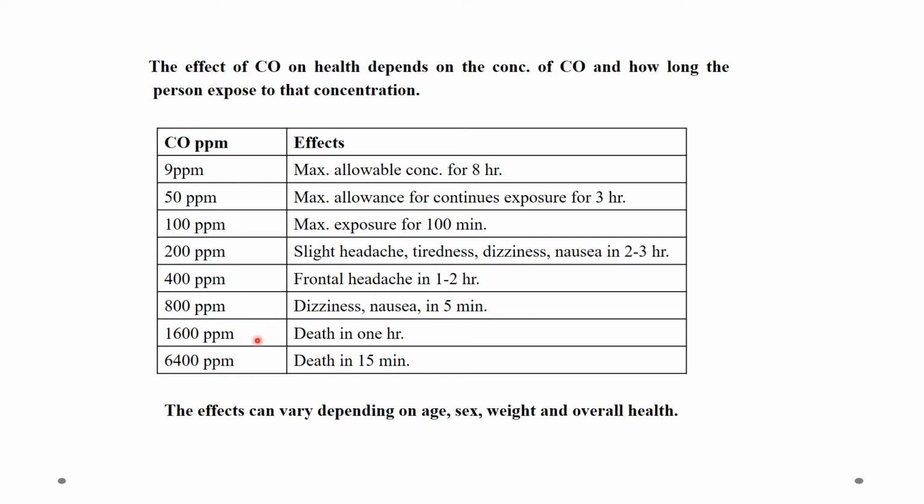If its concentration is 1600 ppm, it may lead to death in just 1 hour. If its concentration is too high, up to 6400 ppm, then it leads to death in just 15 minutes. So this is the effect of carbon monoxide on health. However, the effect can vary depending on the age, sex, weight, and overall health of the human beings.